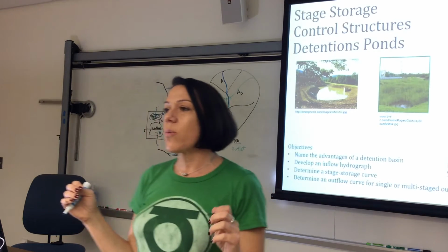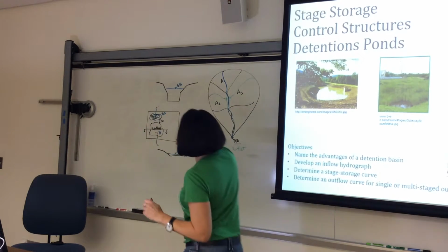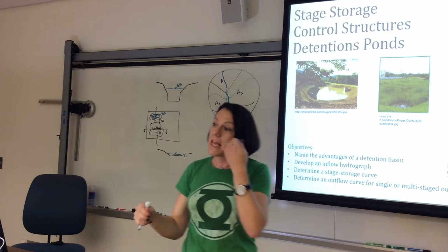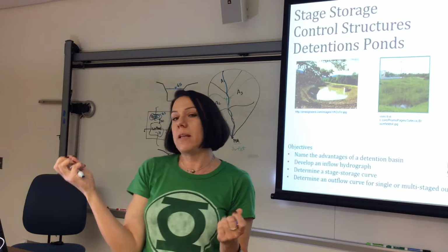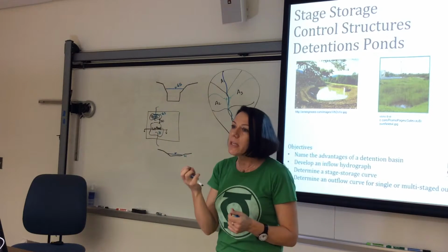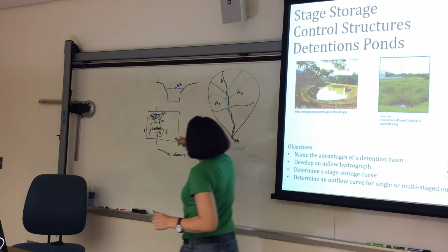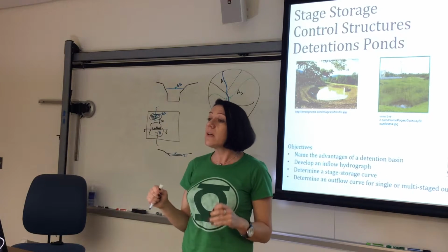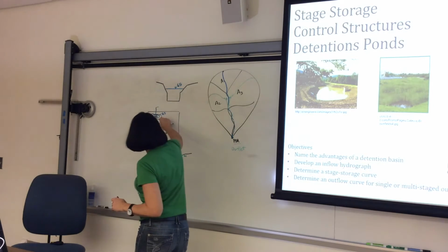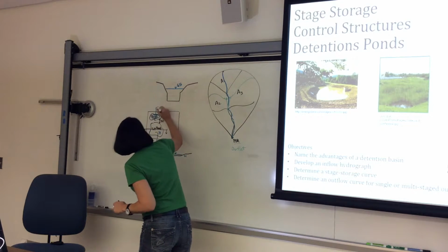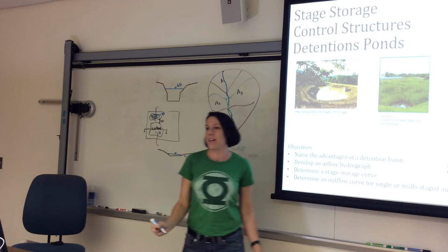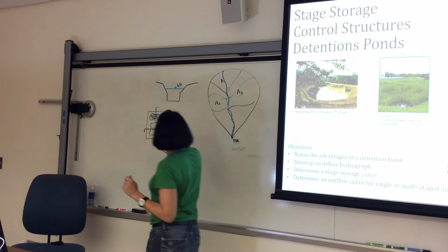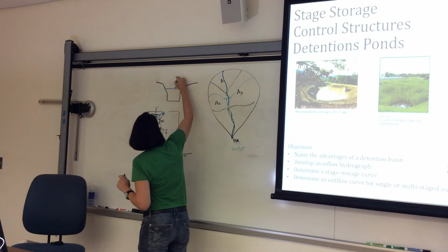Natural gravity in the ground, where do you think the water from this wetland is going to go? It's going to go to the pond, and we don't want that because it's actually sucking water. I mean, that's not a technical term. It's actually pulling the water from the wetland into the pond. And jurisdictions, the water management districts, will not allow that. So typically, if we're that close, you're going to say that control is at least at a 71, so you're not pulling water to the pond. So that would be how our control would be set.